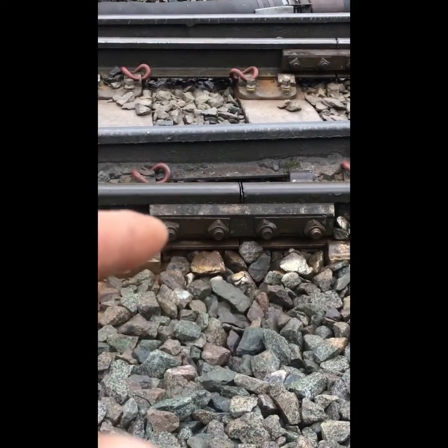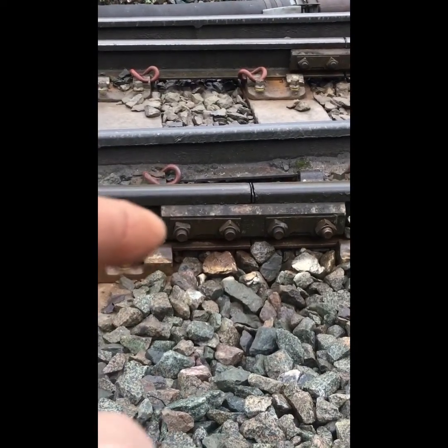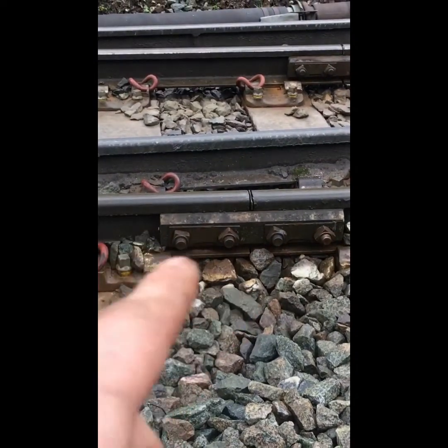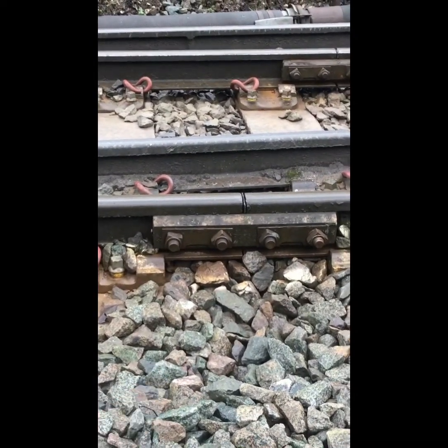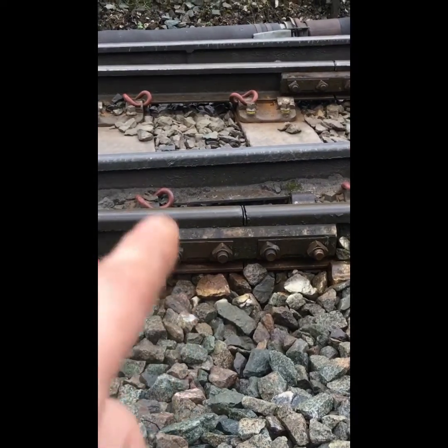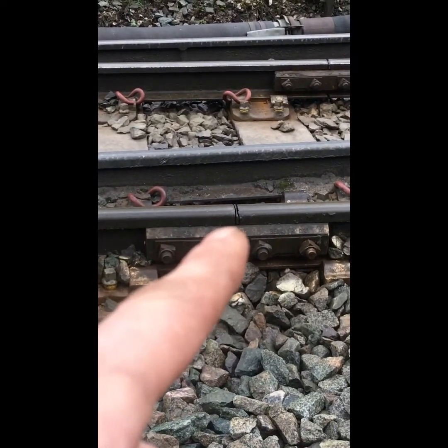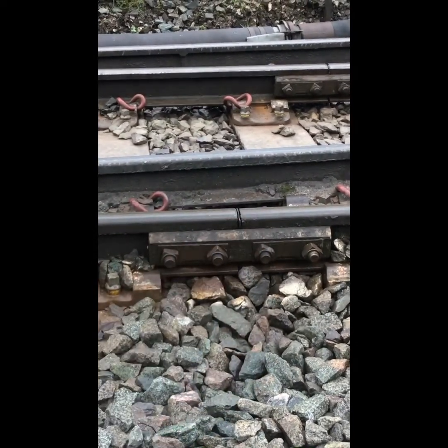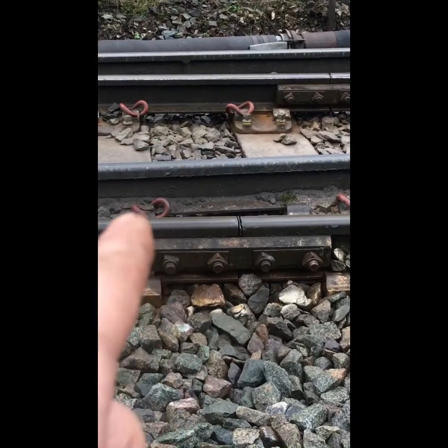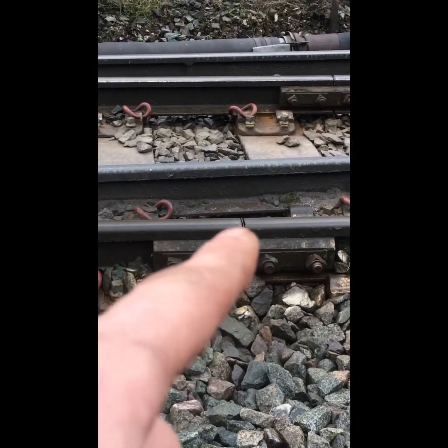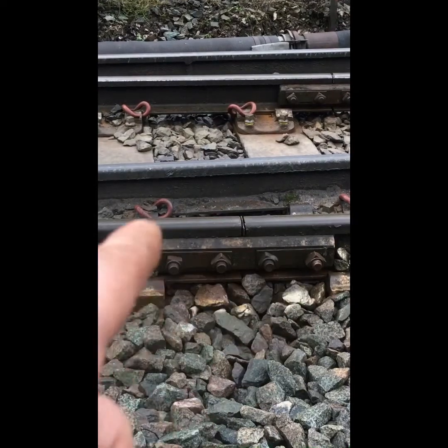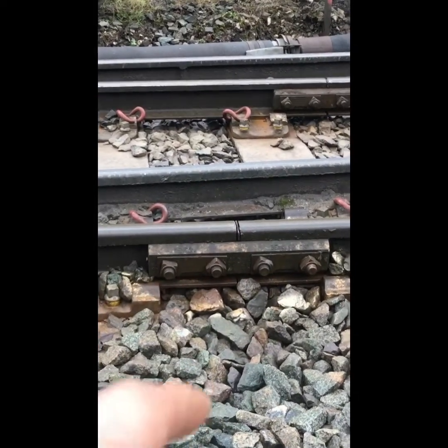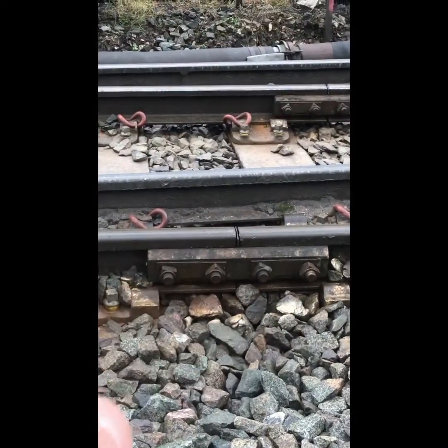When this has been put together, you want to make sure that the bolts aren't smashed through with the hammer, otherwise they will damage the insulations on the inside. Also, if you just drill the rails, you want to make sure you get rid of all the swarf out of it with the magnet, otherwise that will slowly eat its way into the nylon plates. And also in the middle, you'll notice this is a T-piece. Depending on the quality of your track, this can get knocked to heck, and the top of the T-piece starts to burr over. You can get burring faults, small bits of swarf carried across by the rails, the train wearing the rails down, that eventually shorts it out, especially on sharp curves where it will actually carry the swarf along.